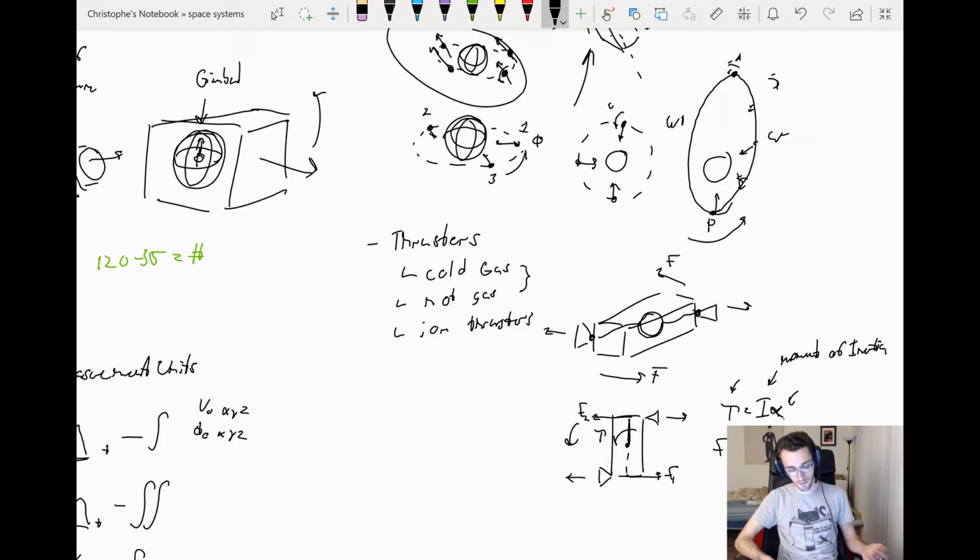So that's how cold gas and hot gas thrusters achieve an attitude change. They're often paired with electronic systems that control the valves on your space vehicle to change your attitude by a certain amount with certain design characteristics, and that goes more into control theory and controller design. But for now, let's just keep it simple. Your computer is controlling when to open and close these different valves for your cold gas or hot gas thrusters, and by doing so, they induce a moment about your spacecraft which changes your attitude. And that's how they work.